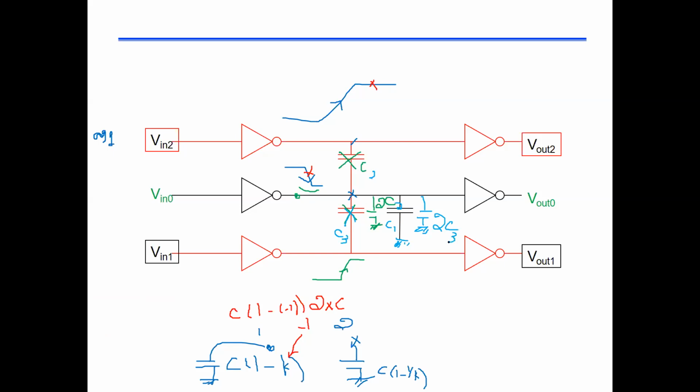What happens is that now my total capacitance at my node, my total effective capacitance between my node and the ground has increased. يعني if someone is opposing me and the wire is close to me, what is going to happen is that it is going to increase my effective capacitance and therefore it is going to slow my signal.